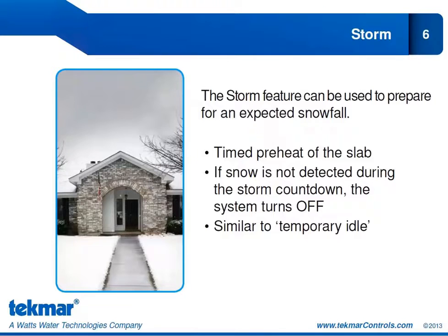Storm, as I mentioned, is a new feature for TechMar. It is similar to temporary idle, if you are familiar with the temporary idle function in our earlier controls. Storm is a timed preheat of the slab. So if you hear on the weather report that we are expecting a snowfall sometime today, what you might want to do is to preheat your slab. So instead of starting from a cold start, we can bring that slab up to a certain set point as entered by the user, and it can stay at that storm set point until it sees snow.